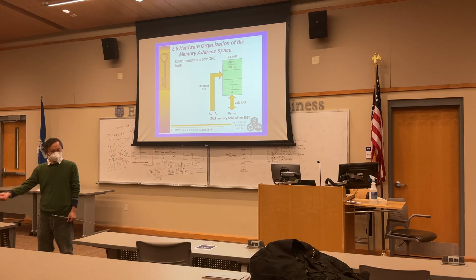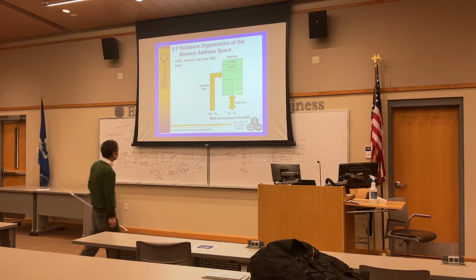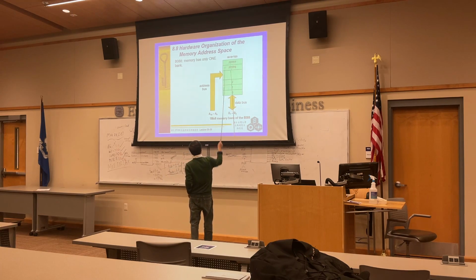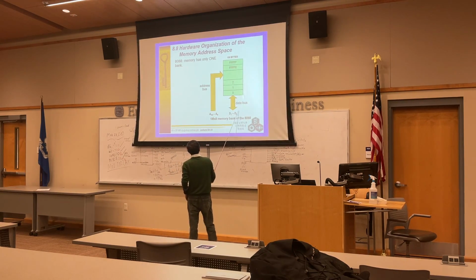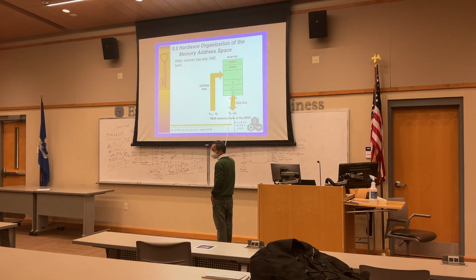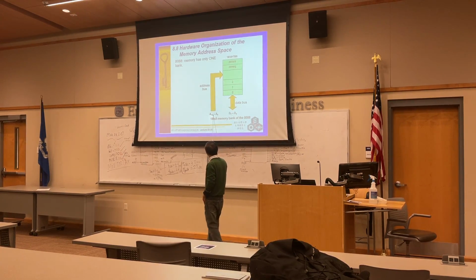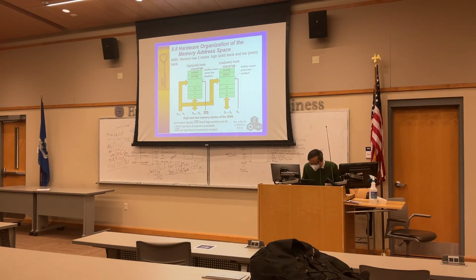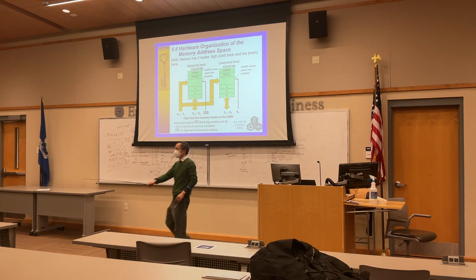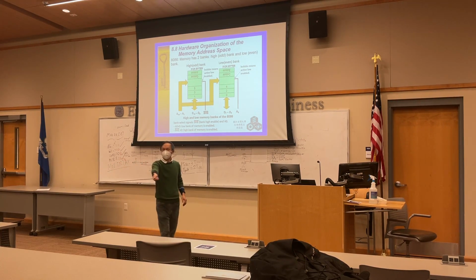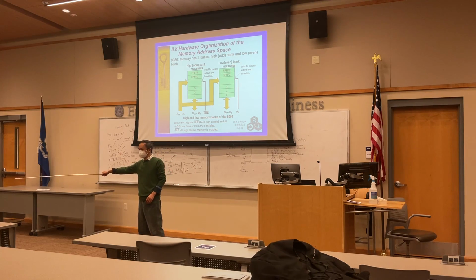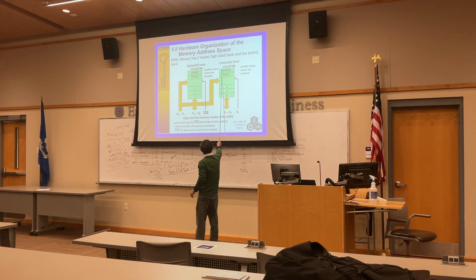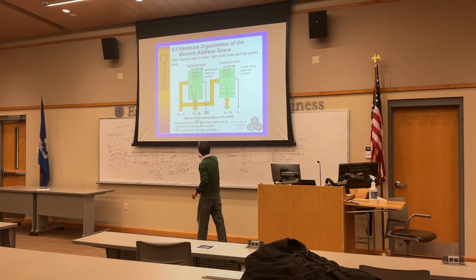From 0000H to FFFFH. The address, the data. Now we have the data bus, bidirectional, 8 bit, here in the 8088. The address bus is 20 bit. If we have an 8086 microprocessor, it's a different architecture. We have two banks: lower bank, higher bank, even bank, odd bank, with the address.